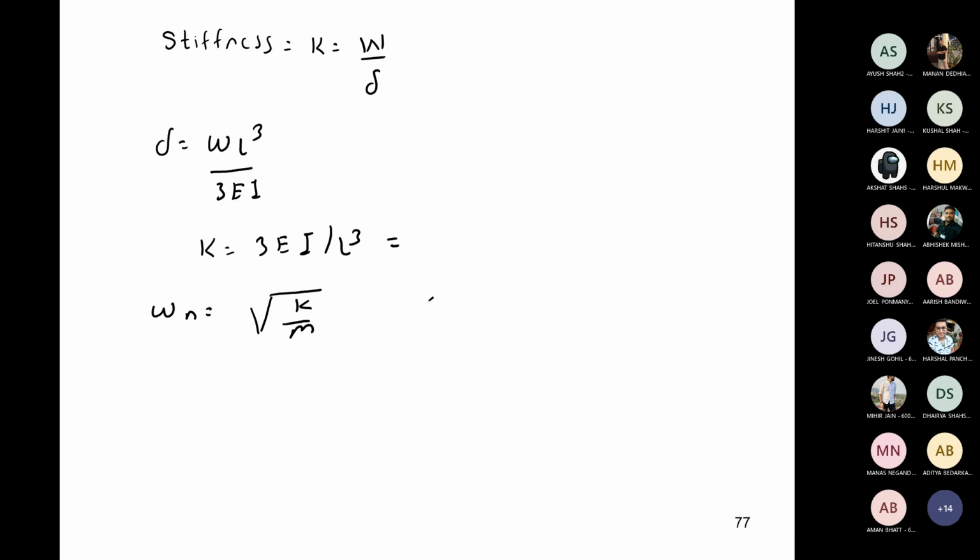And therefore you get r, that is omega by omega n, that is forcing frequency by natural frequency. Okay. Then use the equation of tan phi is equal to 2 zeta r upon 1 minus r square, and find out the value of zeta. And enter that in the quiz. The third question is the damping ratio.